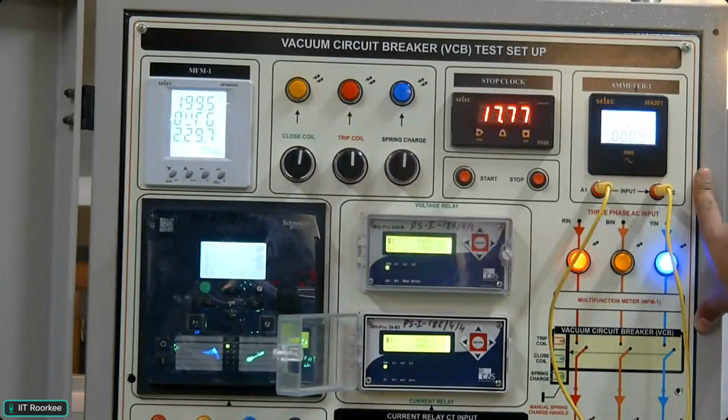Otherwise, the pickup current value is 1 ampere, and our fault current here means it is an overload condition. We cannot say it is a fault, but if the overload is too much, or happening very rapidly, that's why we consider it as a fault. So if we do it for 2 ampere, for 1 ampere it is a 100% increase, so we are considering that as a fault.